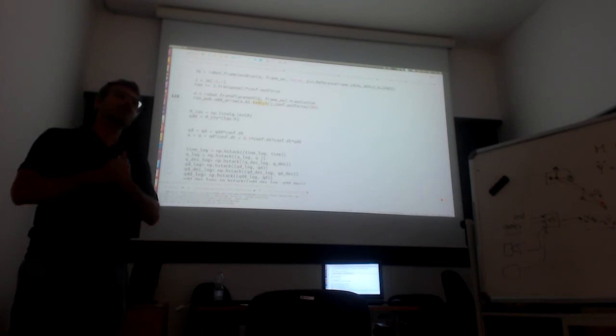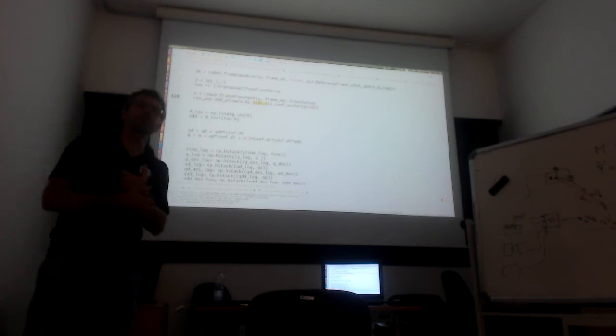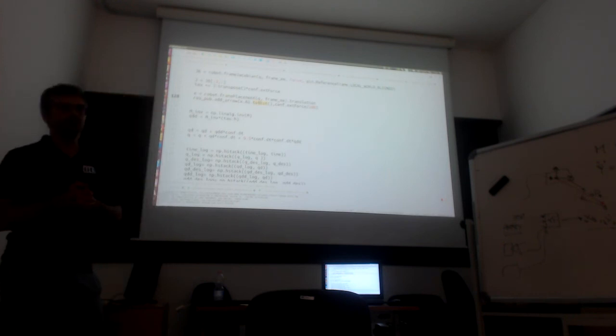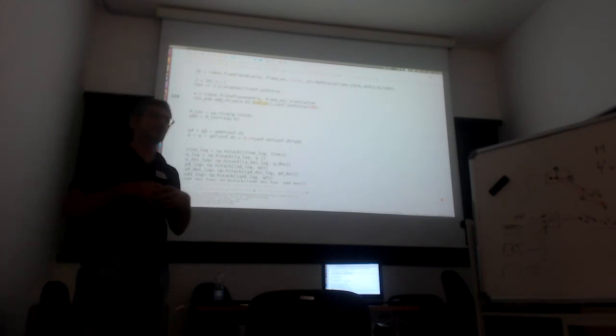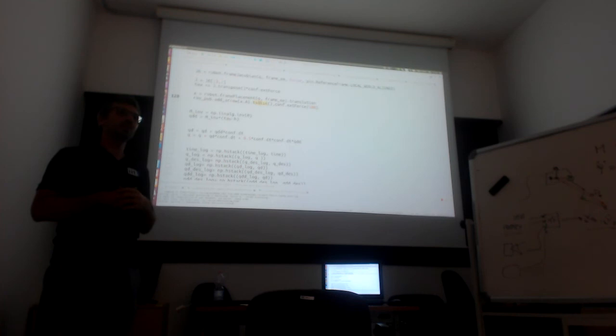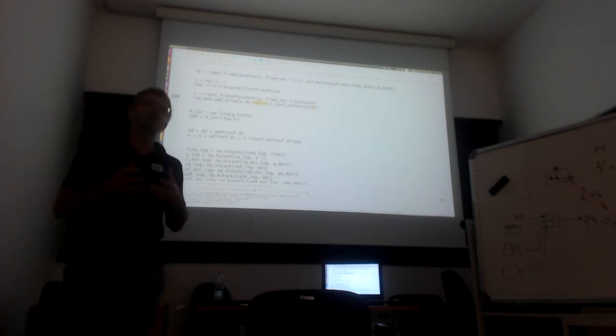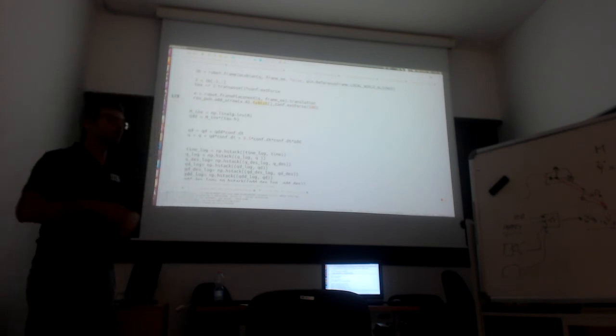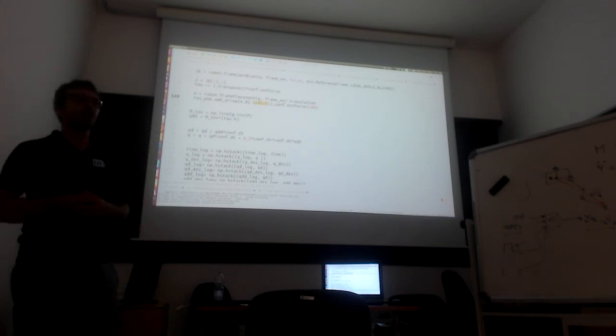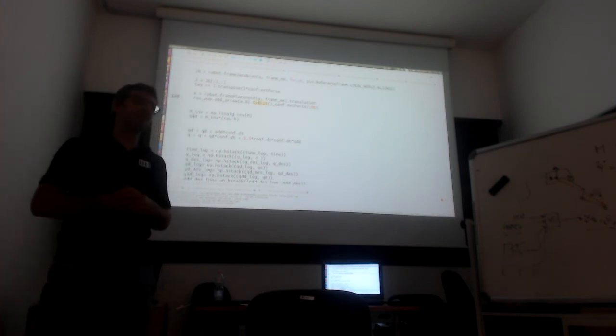And we have matrices that depend on the joint configuration. And we saw that using inverse dynamics, we are able to invert these nonlinear, joint configuration dependent dynamics, and eliminate these couplings, and still close the loop with our desired controller, the centralized one, and achieve a nice tracking even with low gains. While if we have these couplings, we need to increase the gains to reduce the influence due to the couplings.